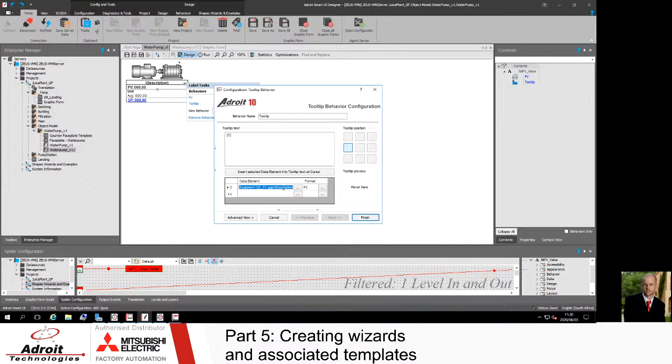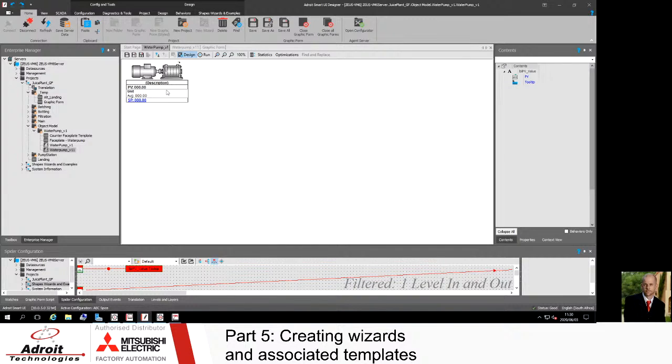So I pull back the agent and put a description for this particular pump, the agent description, and I can then display that above and beyond the static description in there, guys. This description could be just a P&ID number if you want. I know some guys like to put that on their screens so they can reference what equipment they're looking at versus their drawings. That gives you a little bit of flexibility, but I've just gone with the description there.